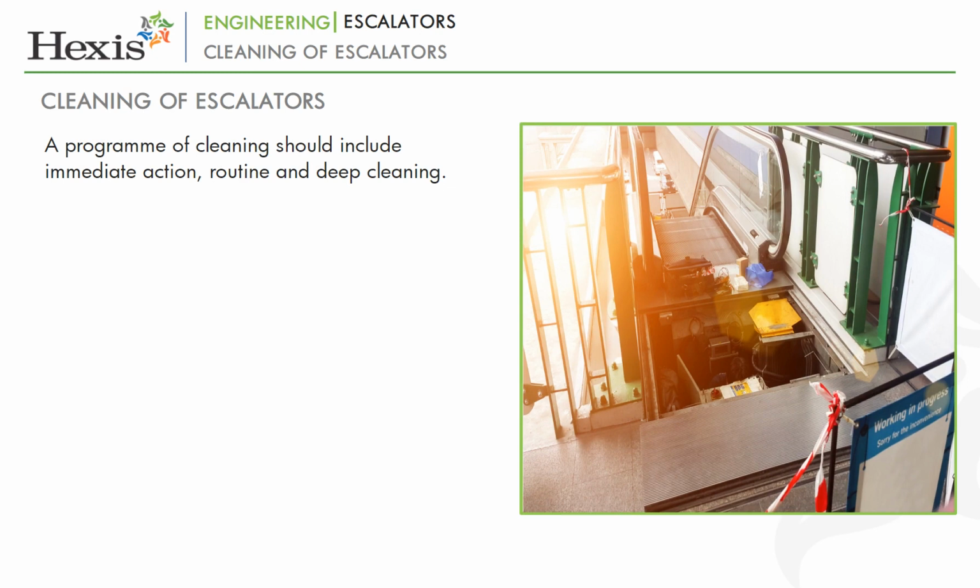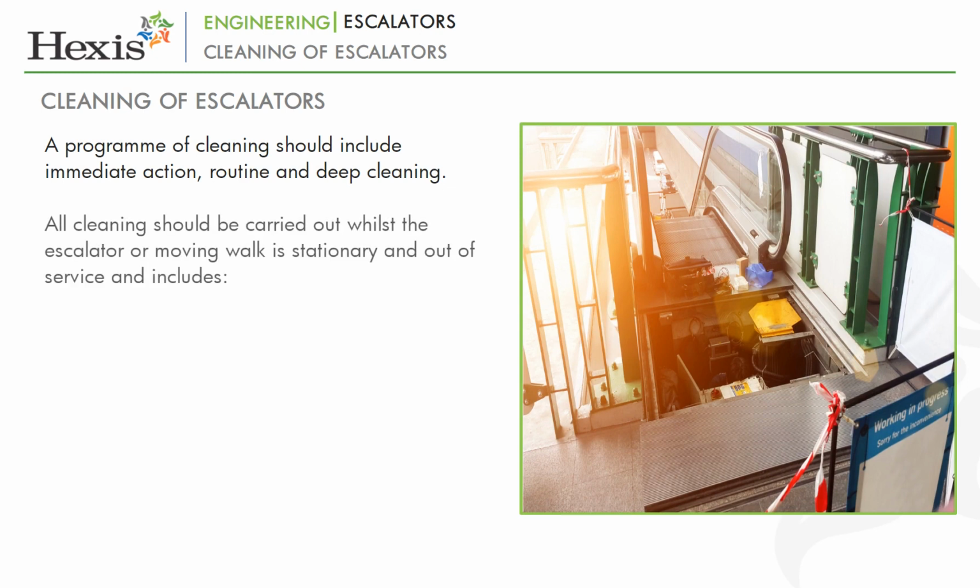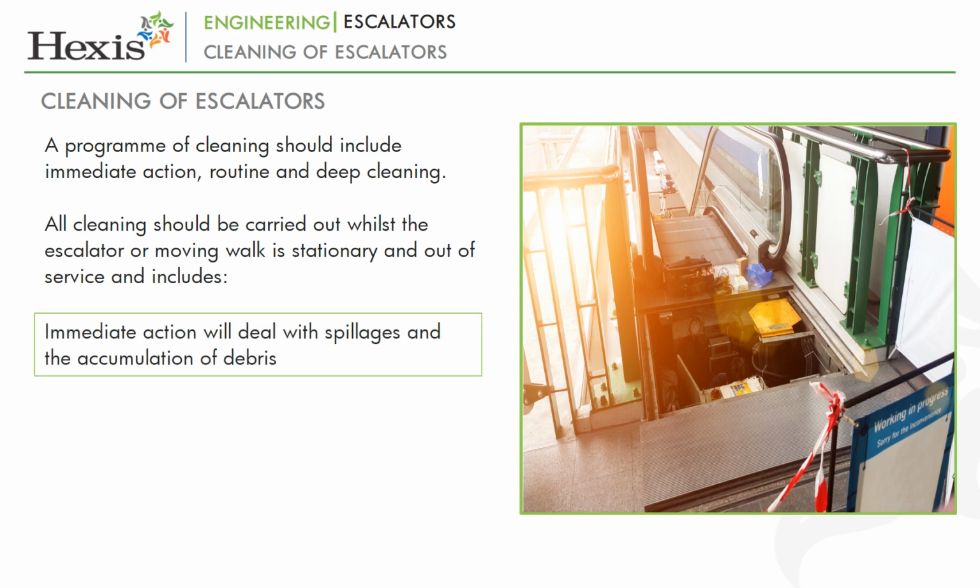A program of cleaning should include immediate action, routine and deep cleaning. All cleaning should be carried out whilst the escalator or moving walk is stationary and out of service and includes immediate action, which will deal with spillages and the accumulation of debris, etc., as these significantly increase the risk of slips and falls. These should be cleaned up or removed as soon as possible.